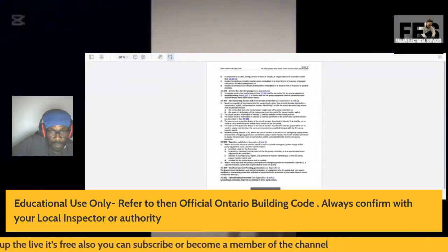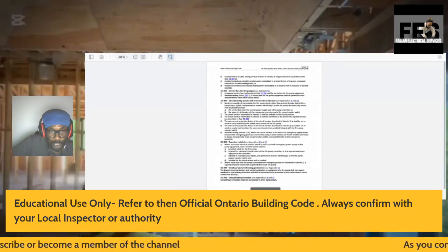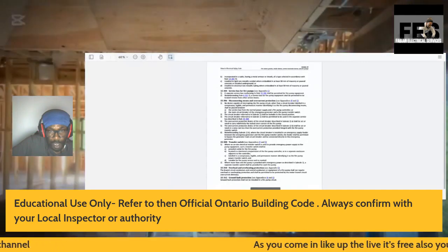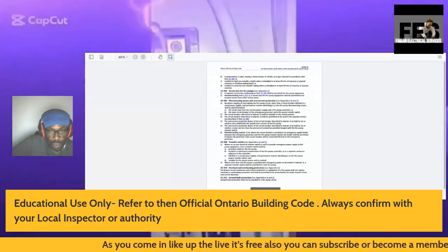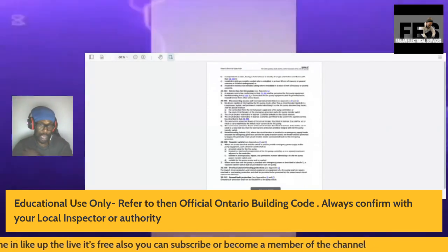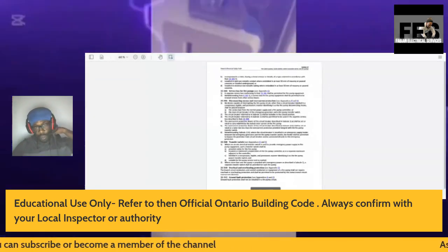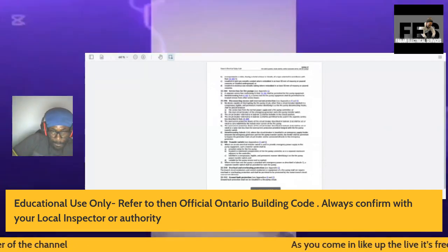The circuit breaker referred to in Subrule 1 shall be lockable in the closed position. The circuit breaker referred to in Subrule 1 shall be permitted to be used in the separate service box described in Rule 32-304. So it's giving you the rule you can do, but it's also telling you to refer to 32-304.